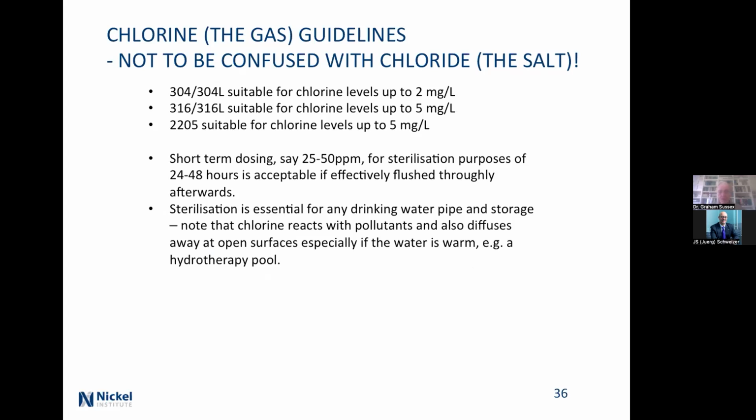It will also diffuse away from open surfaces. So if you're looking at a hydrotherapy pool and it's not used for a while, then you'll find that if there's a handrail going down or a vertical pole going down, in the area around that pole at the water level, you may well wind up with a bit of corrosion simply because there's too much chlorine in there and the level is immediately above. The chlorine just diffuses out and then drops into condensation.